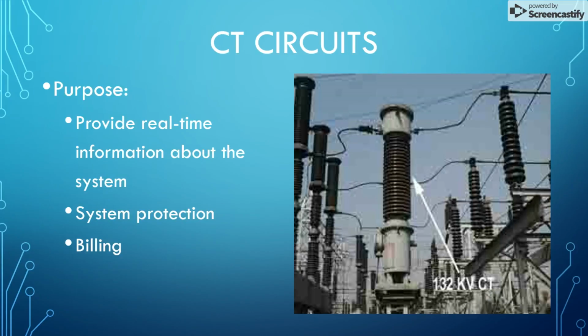The purpose of CTs is to provide some real-time information about the bulk electric system. And it's going to do this in a couple of ways. It's going to do this through system protection so that we're able to see and detect faults on the line, and abnormal conditions in the case where we need to remove a line from service or a particular portion of a substation from service.